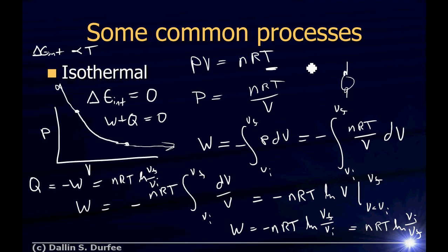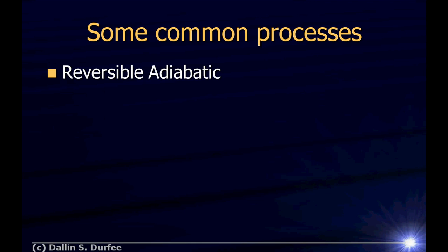How do you do an isothermal process? Take a piston full of air and compress it while that piston is in ice water, and do it slowly so that as this piston tries to heat up, heat flows out and it stays at 0 degrees C. All right.